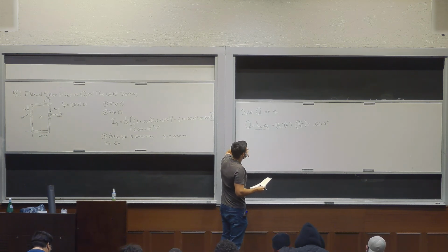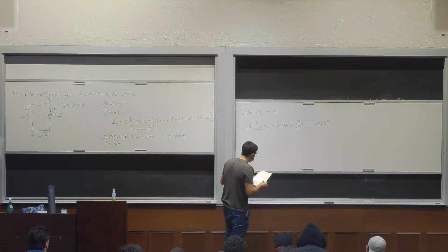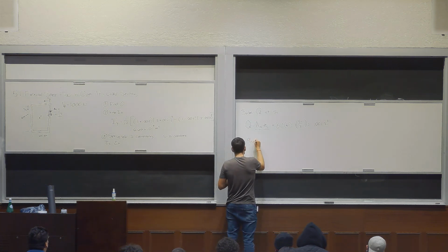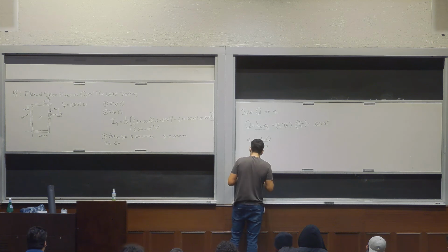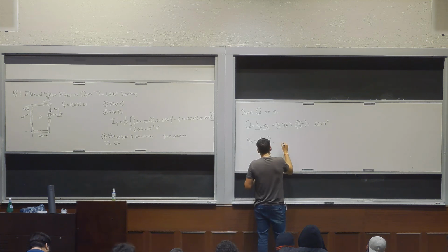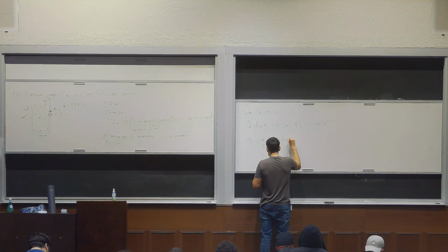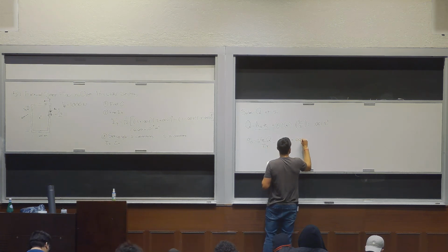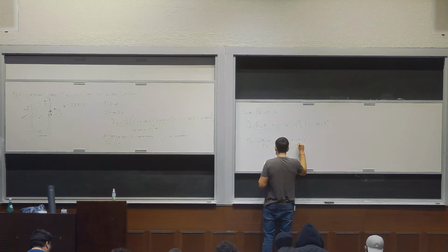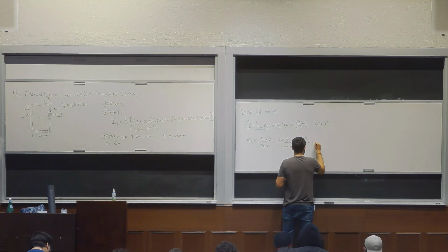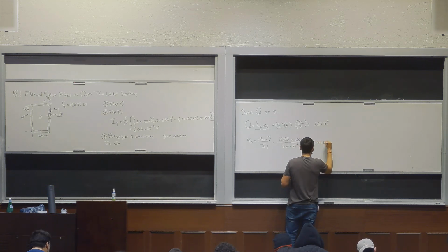The goal now is to find shear flow. There's a relationship between those. So q_s equals negative V_Z times Q over I_Y. And so we plug in the numbers here: 1,000 times 0.001 S1 squared, over 6.66 times 10 to the negative 6, equals negative 1.5 times 10 to the 5 S1 squared.